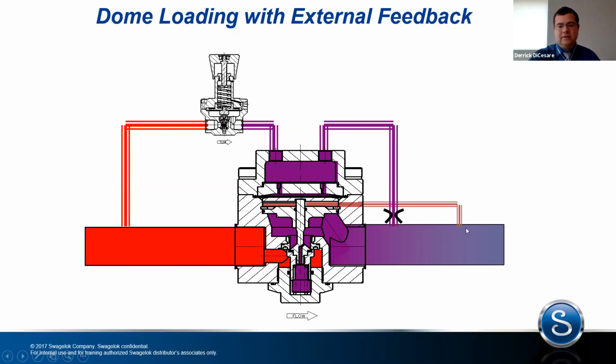Down here we're at 95. This line is going to send that pressure signal back here saying, hey, we need more pressure. Open this up some more to get a more representative pressure down here. So we're adding another force to our balance equation.